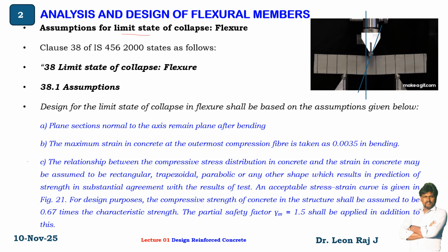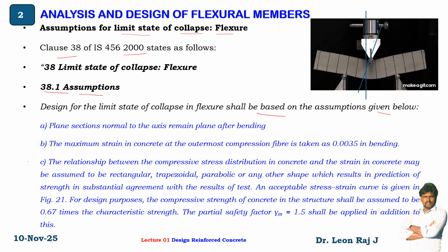Assumptions for a limit state of collapse, that is flexure. This is under clause 38 of IS 456-2000. So 38.1 states about the assumptions. Design of limit state of collapse in flexure shall be based on the assumptions given below.